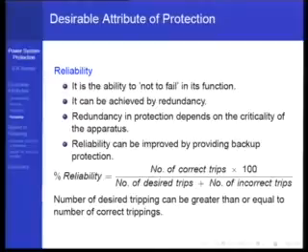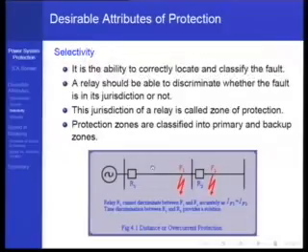The other way of providing reliability is to do a backup protection. So backup is at another terminal, at a distant place. Another bus, a relay, like for example here, a relay R1 can be used to back up fault protection on this particular feeder segment. Why should you do that? Because if you do a local backup here, duplicating with another protection system, it still doesn't mean that you are 100% sure that you have provided a backup protection.